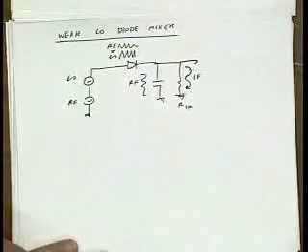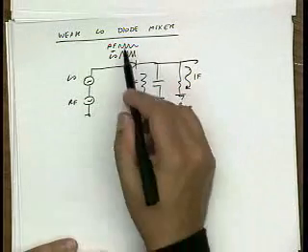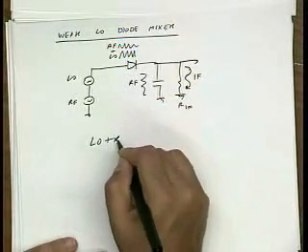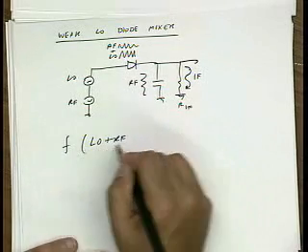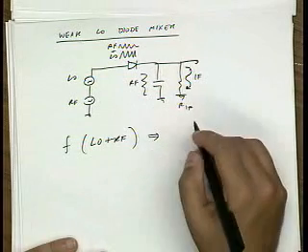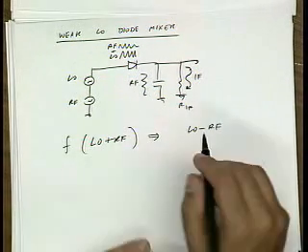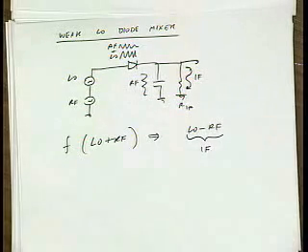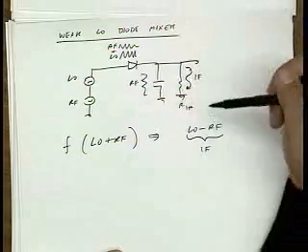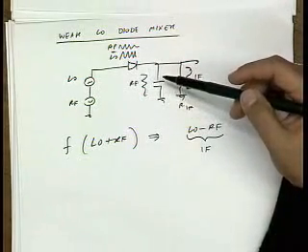Okay? So, you guys know that any kind of nonlinearity will actually generate mixing. I have LO plus RF, and then I go into some nonlinear function. I know my output is going to generate IM products like LO minus RF, which is my IF term. The difference between this circuit and the previous circuit is the conversion gain of this circuit is going to be quite a bit lower, right?